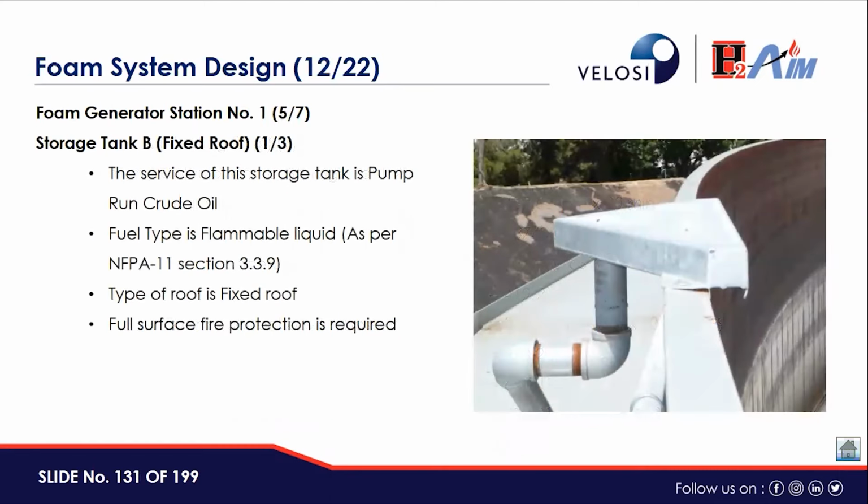Similarly, we calculated this for fixed roof tank B as well. The service of this tank is pump run crude oil. Fuel type is flammable liquid. Fixed roof, full surface fire protection is required for this.